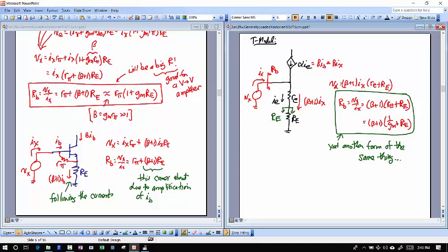So in other words, if I put a transistor there, which you will have every now and then, if I'm looking down this way, what do I see? The big RC, but in the end that's little R naught for this, because that's going straight to ground. It won't be if I have an emitter resistor there. And so we're going to get very general after this. I'm showing these resistors, but those resistors could be small signal resistors from other transistors.